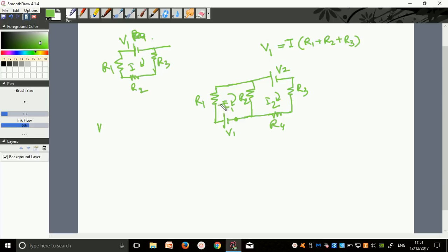So whenever current is flowing through a resistor, it is going through a potential difference, right? From the higher potential to the lower potential, the current flows. So if I1 current is flowing, the drop is from this side to this side. So I will calculate I R1. I R1 is plus to minus, so positive to negative. When I'm adding, these will all be within the mesh, there will be a vector addition. So from positive to negative, if we are moving, so I1 times R1, it is going down. You can take any of the nomenclature, but you should follow one. So I am taking from plus to minus, I am going down, so it is minus I R1, negative I R1. You can say this is also plus to minus, this is coming down.